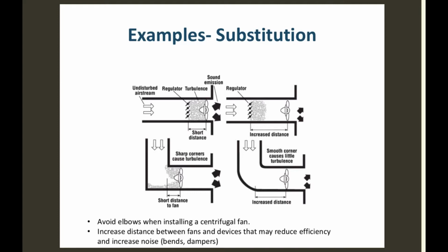The velocity is too high, right? You know what? These diffusers on the side here, we don't have in this room. They're taking the place of ceiling diffusers. With ceiling diffusers, the air comes down, and you'll notice that there are little curved vents in them. So instead of going straight down and hitting you in the head, they diffuse the air, it turns and curls, and the air mixes. For most of them, each one only has maybe a couple hundred CFM, cubic feet per minute, coming out of it.